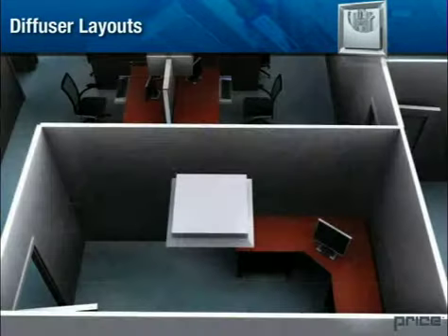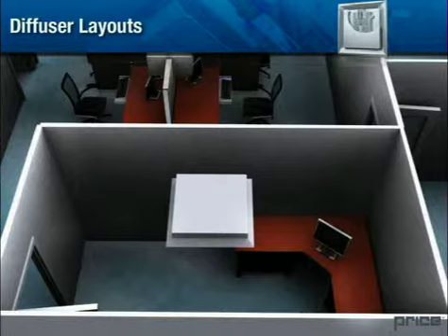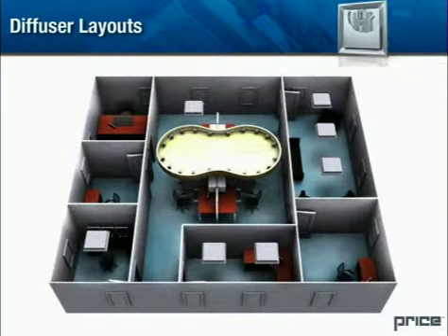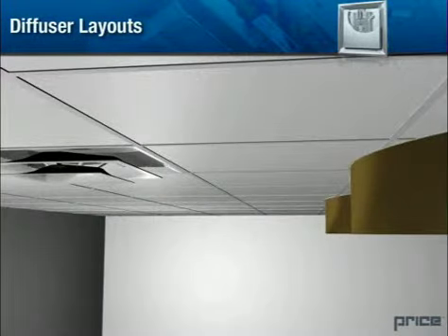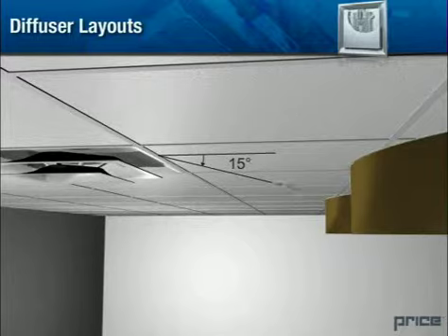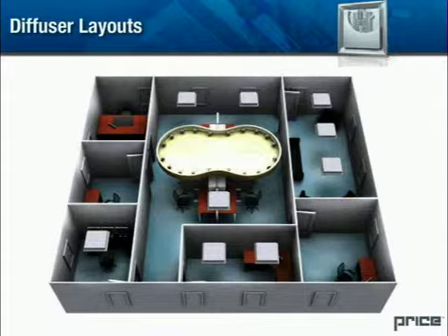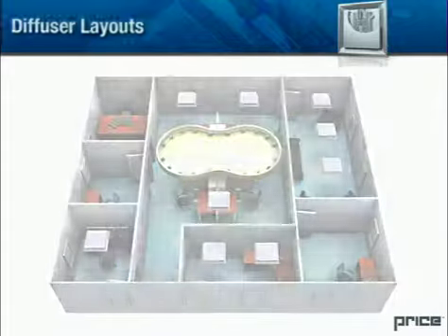3. Undersupplying. When dealing with larger rooms, try to use more than one diffuser to supply air to the space. Believing that money will be saved by putting all the air through one diffuser will cause more problems in the future. 4. Ceiling obstacles. Generally, ceiling obstacles should never drop lower than 15 degrees below the edges of the diffuser. The discharged air will be affected by bulkheads or ceiling obstacles that do not follow this rule. Moving a diffuser away from the ceiling obstacle decreases the effect on the airflow.